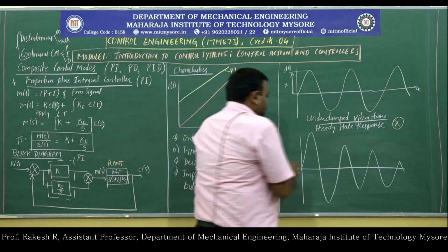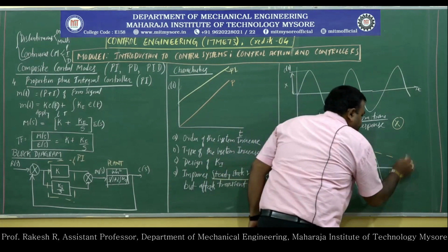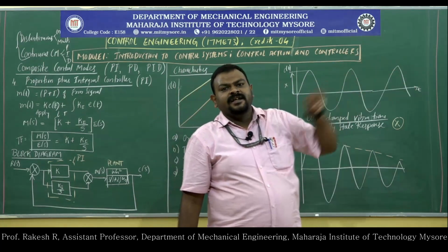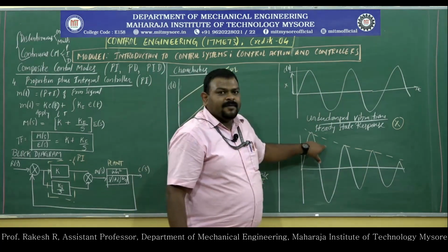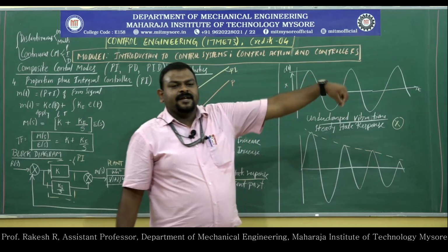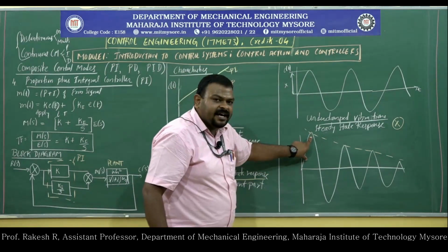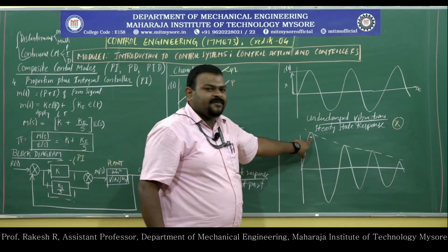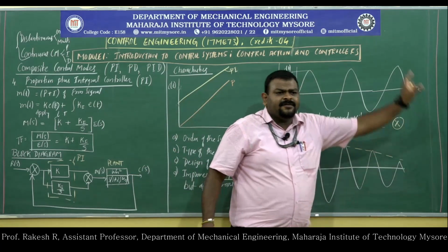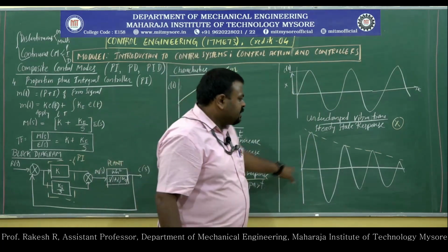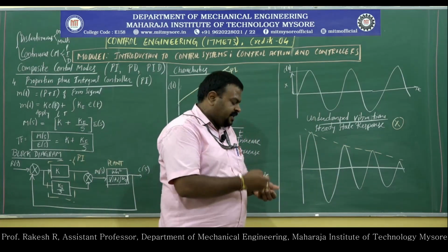If you take the amplitude graph, the amplitude will be decreasing exponentially. The corresponding term used is the logarithmic decrement of the amplitude. So initially I want a higher amplitude to overcome the inertia force of the vehicle, then after that the response should be slow and the amplitude should decay. This is the graph for a stable system.